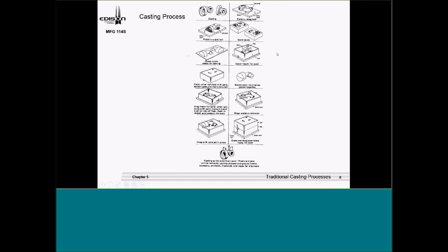I have a paper that I pass out with what they need to do in lab. They'll see their pattern as we come up here, and they put it on the bottoming board, or the splitting board, I'm sorry, actually no, it's the bottoming board. Then they'll put the cope half on, and we'll ram the sand, as you can see. When we put the sand in there, we'll put some baby powder in as well, and the baby powder helps us release the pattern from the mold.